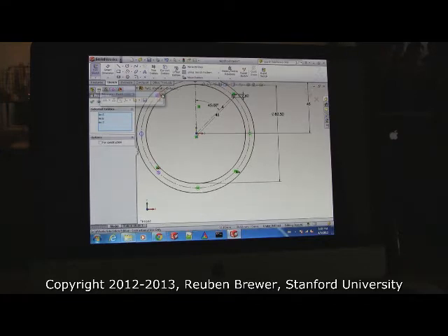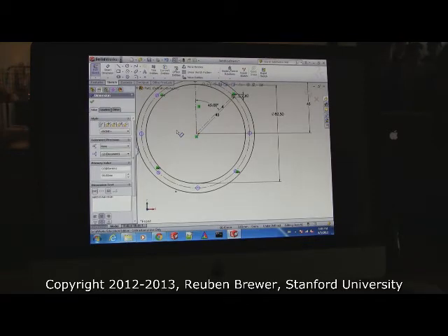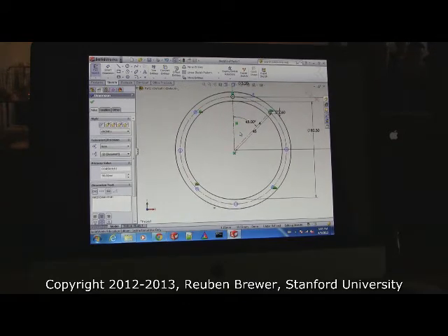That makes sense. Okay, so everyone's screen should look like mine and tell me what the problem is. Holes are still blue. So, and again, this is pretty advanced. At this point, let's just do that, okay? There are two buttons up here. Everybody look at my screen. This button says I'm done with the sketch, I'm ready to extrude it. That's a good button. This button means I screwed something up, I wish to cancel. I don't remember if by default it will close out without giving a warning. I'm not going to test it here and now. Don't press that button unless you're willing to lose that sketch and not save any of it.